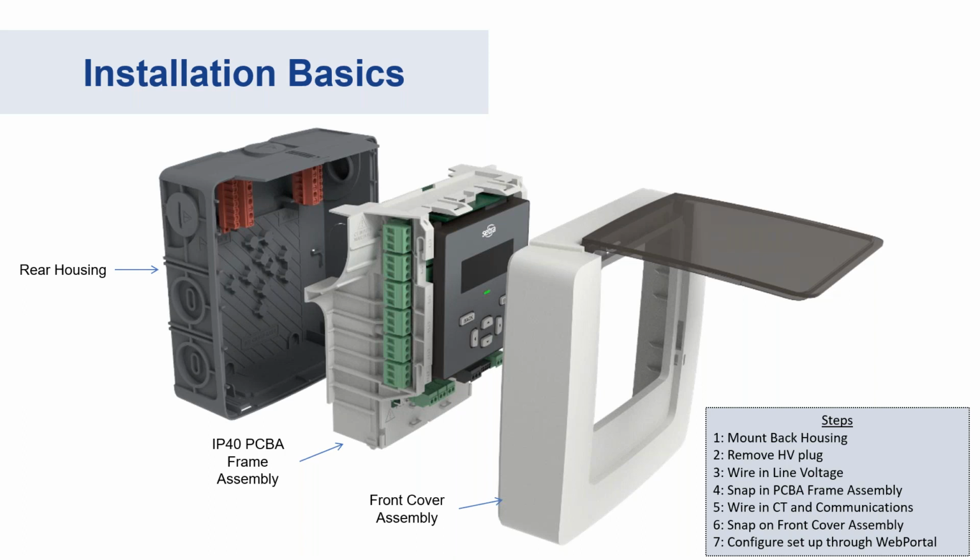How does it handle time of day metering? The meter itself will retain the time of day. There's a real-time clock built into the meter itself. Once you've set that clock, it's going to timestamp all of the values for objects that you're going to be able to access and load to your energy management platform.